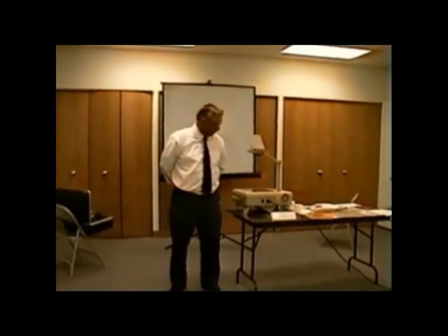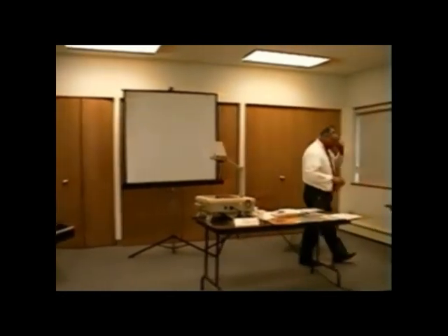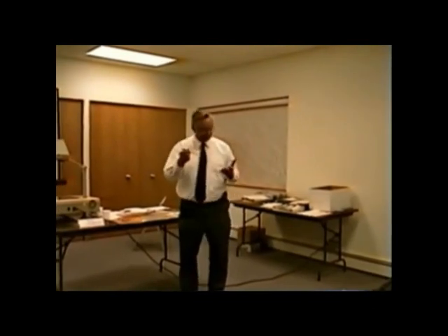All right? But when we ask the technician, what's the gas pressure, a technician may say, well, I don't have a gauge. We say, well, why do you need a gauge? Teach them how to make one over the phone. You can make a manometer gauge, ladies and gentlemen. Let me come over here on this side and just very briefly explain how to make one. You take a piece of copper tubing. And on the copper tubing, you take something to etch some marks in here. You can take a permanent marker and etch 1/4 inch increments.